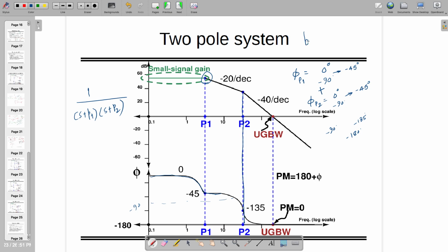And when you do it in the Bode plot, you can see the concavity at 45, this one downward. I made it in software where I was not able to make the sharp line. That was the problem. Otherwise, it will be like this. You can see that in the Bode plot in MATLAB. That will be the correct result. I'm just drawing the approximate results right now. This is an approximation, and I'm teaching you the intuitive way to tell whether your system will be stable or unstable.